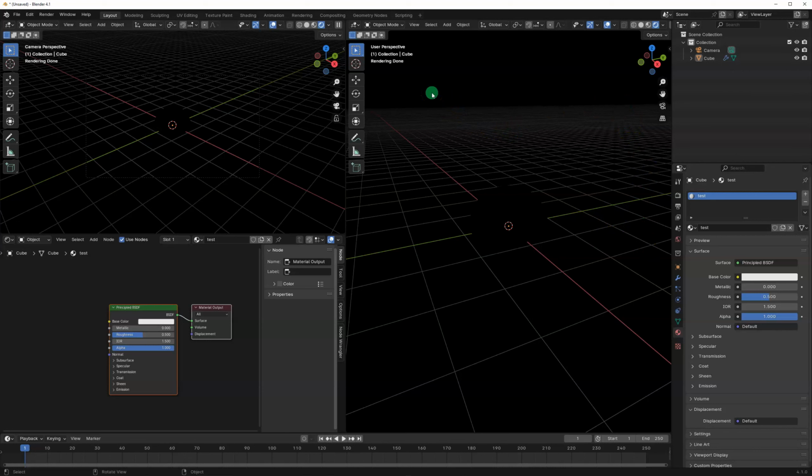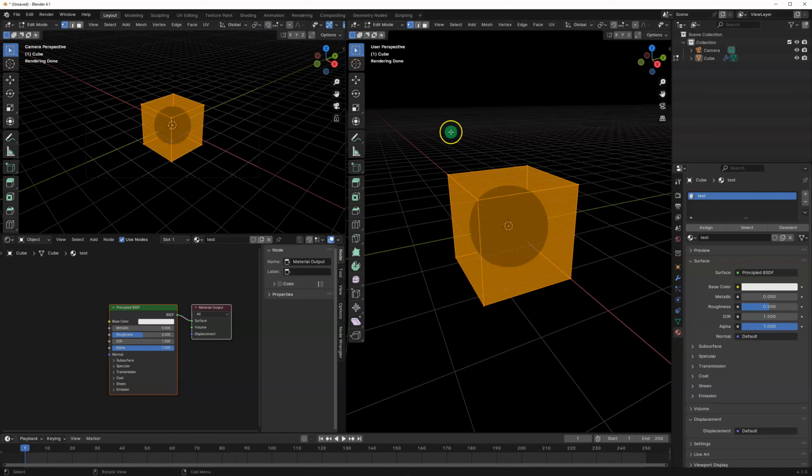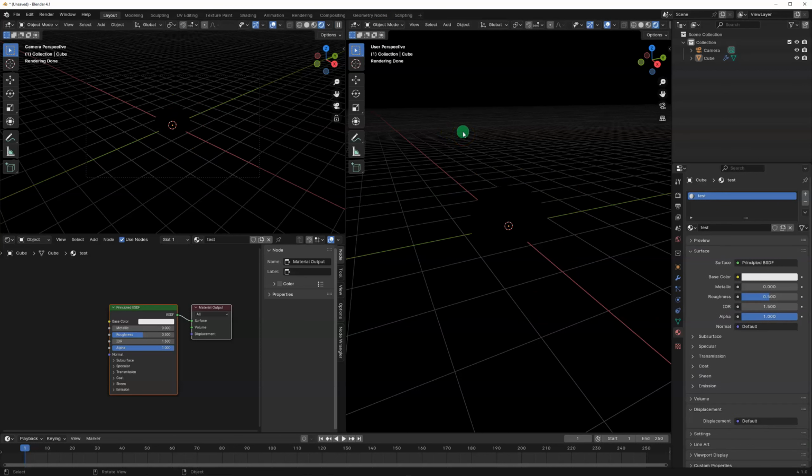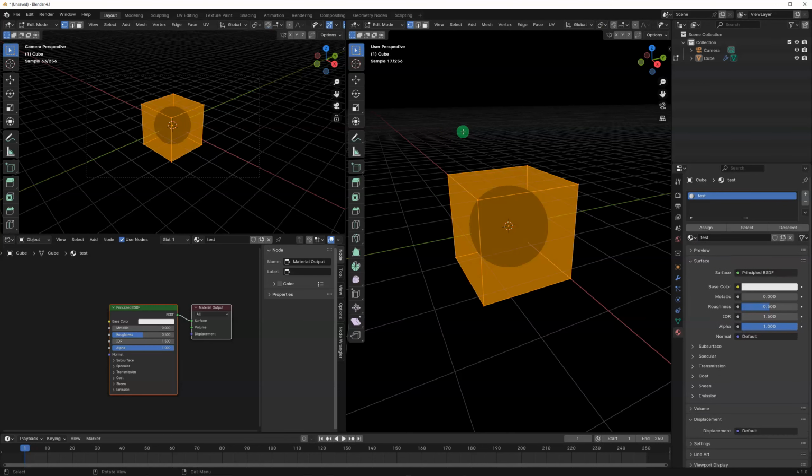so the important thing to remember, and there's two of them, is that we need to look at what mode we're in. So here we're in object mode, and we can also go into edit mode. And the shortcut is pressing Tab on the keyboard. So in edit mode we can edit all of these edges, and we can also in edit mode change the UV values.